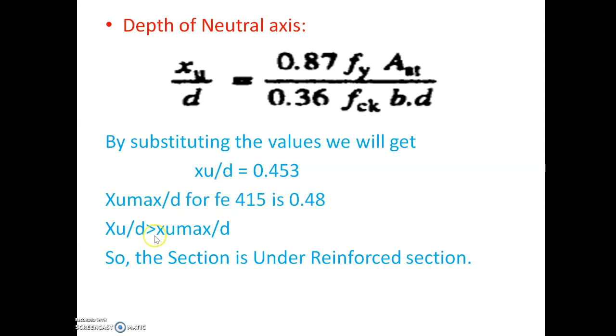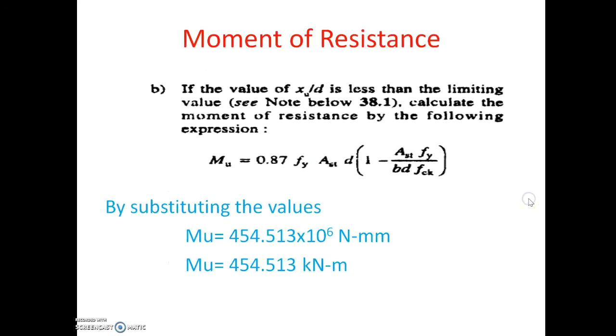Compare the values and in this case xu by d is less than xu max by d, so the section is an under reinforced section.